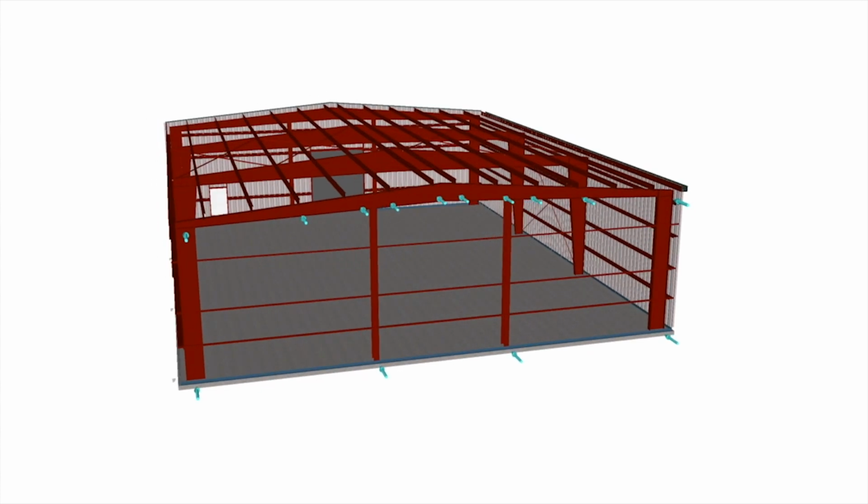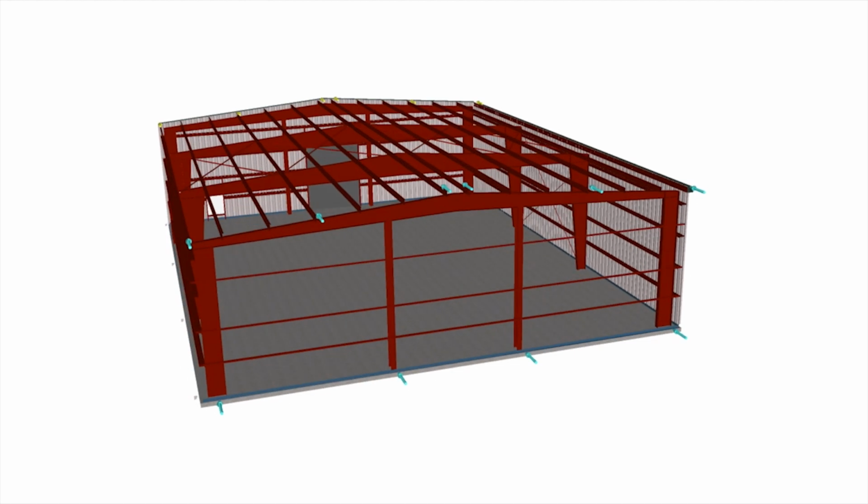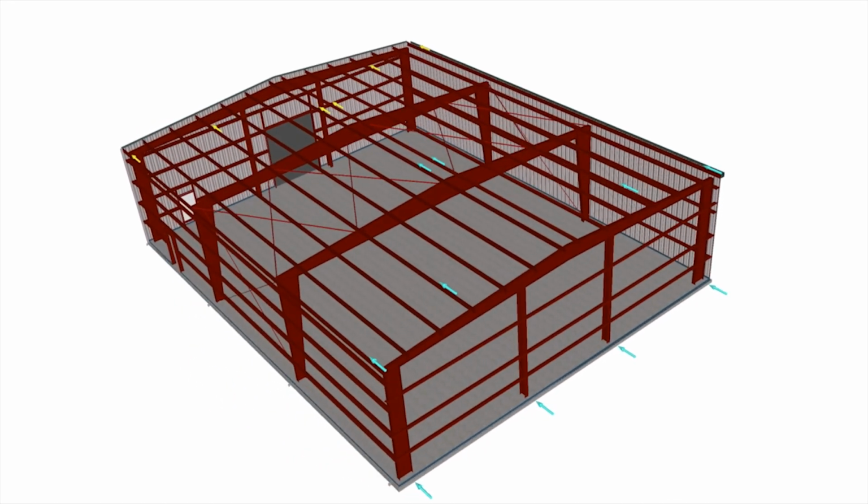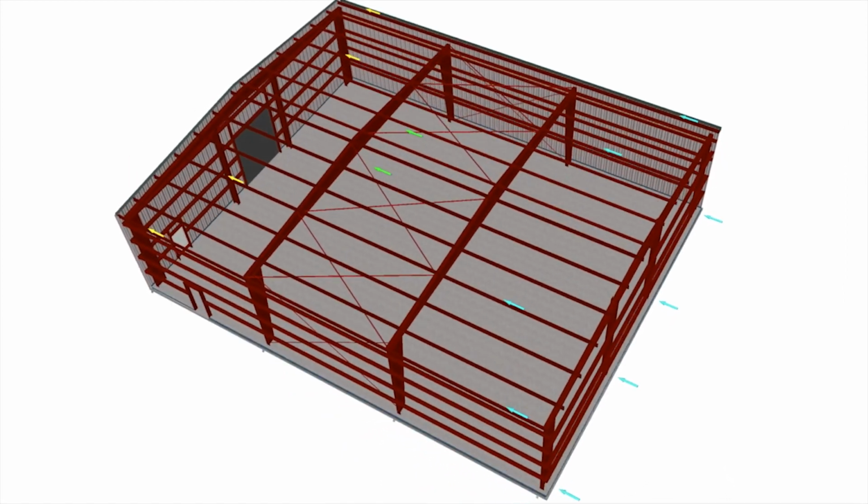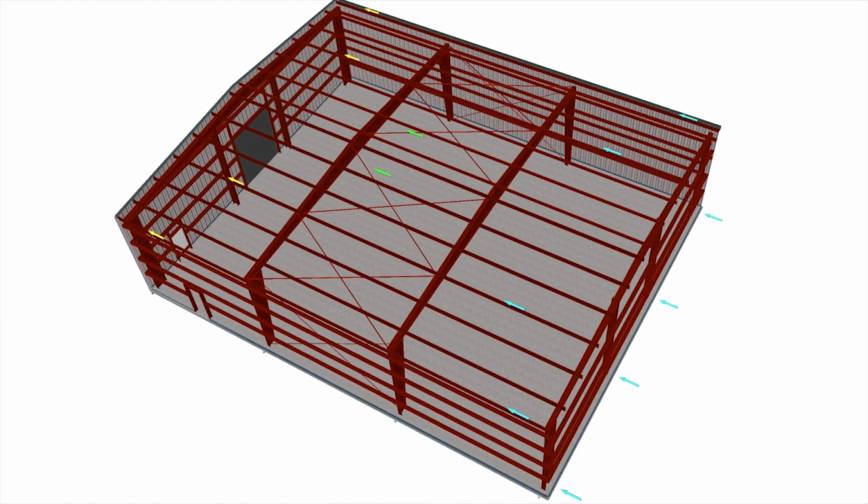Half of the loading on the columns and end post is transmitted downward directly to the foundation, and the top half is transmitted to the rake beam that is supported in the longitudinal direction by the strut purlins and eave strut, shown in blue. Remember that the strut purlins are the heavier purlins that are aligned with the anchor points of the X bracing in the roof, which is where the load is next headed.